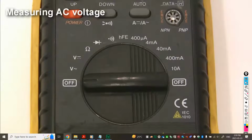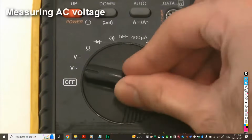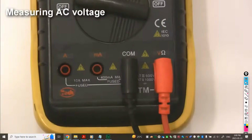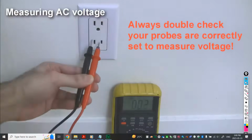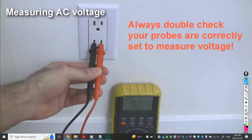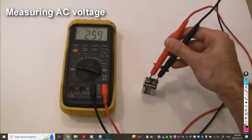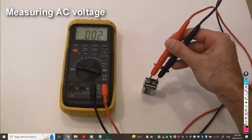Okay, let's move on to measuring AC voltages. Set the dial to the AC voltage setting, and again make sure the red lead is in the jack labeled voltage. Touch the probes to the AC voltage source that you want to measure, and you'll get your reading. As long as you don't touch the metal parts of the probe or short them out, this is perfectly safe. And as you would expect, there's no AC voltage coming out of this DC battery.